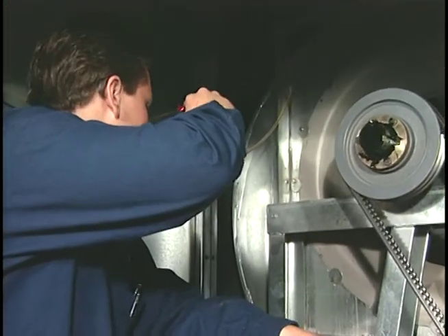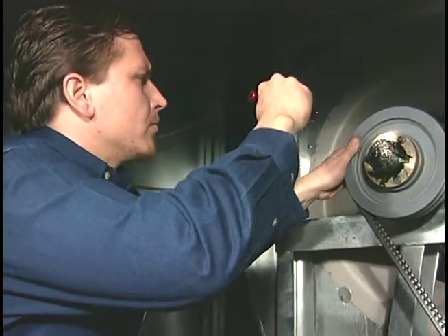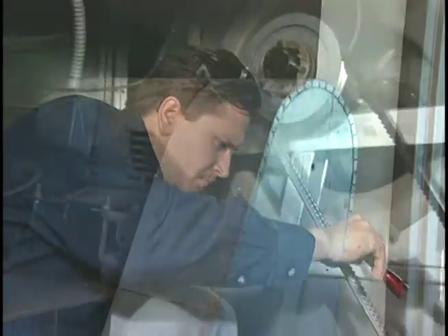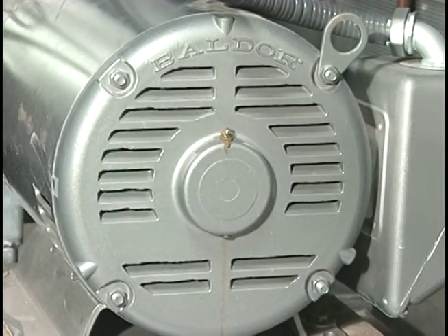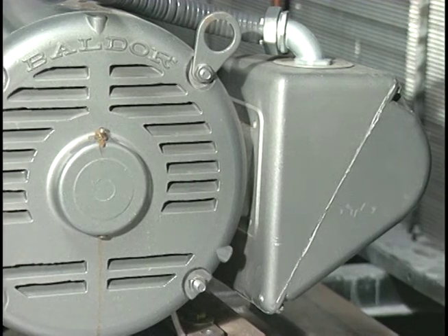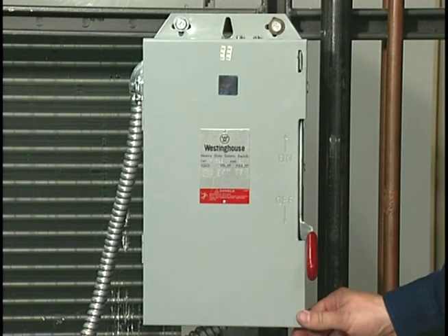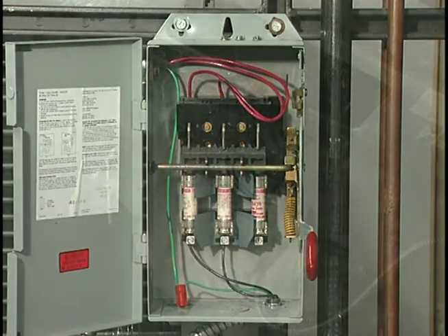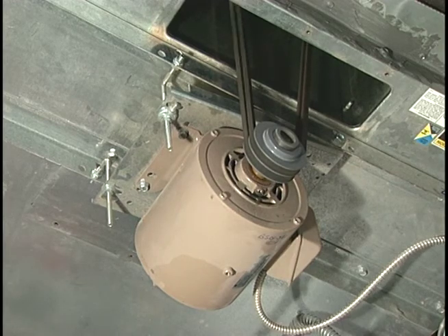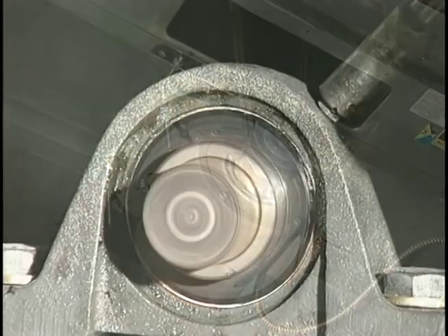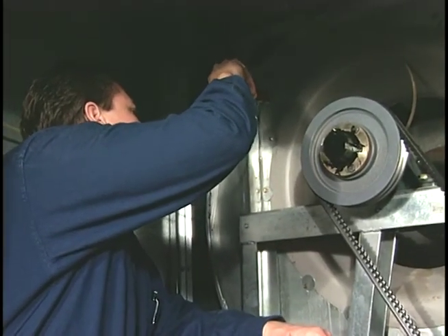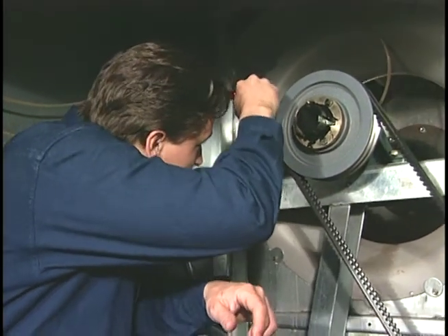The technician checks that sheaves are properly aligned and tight on their shafts. Belts are adjusted for correct tension. Belt guards are properly installed. Motors are wired and energized. Proper starter and overload protection are installed. Correct fuses are installed. Motors are properly secured on their frames. Fan and motor bearings have been lubricated. Fan wheels are aligned correctly with proper clearance between the wheel and the fan housing.